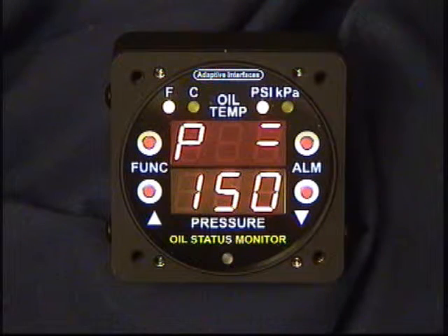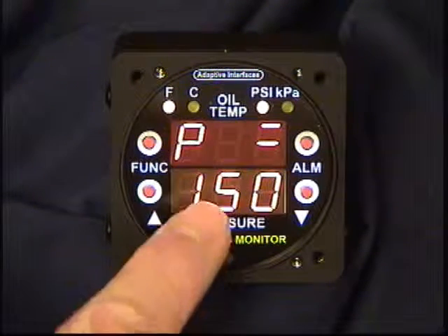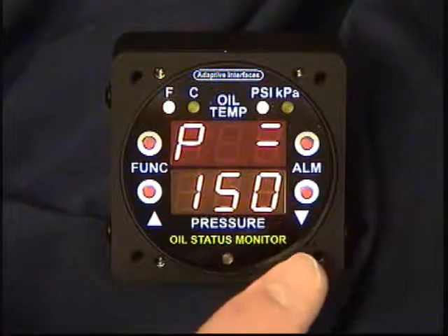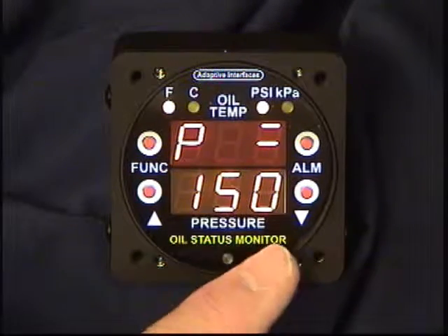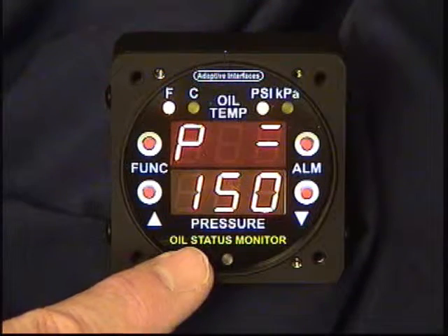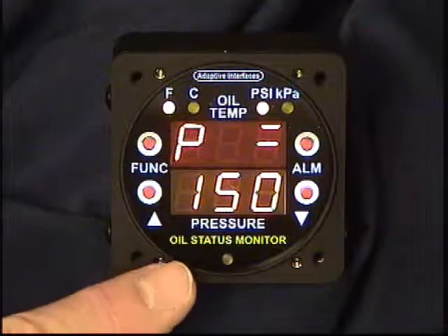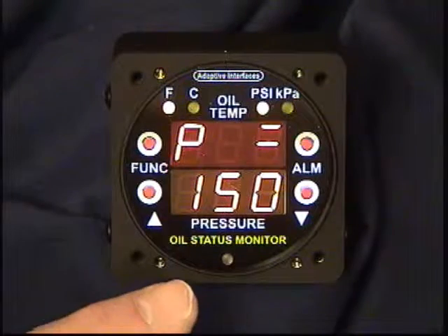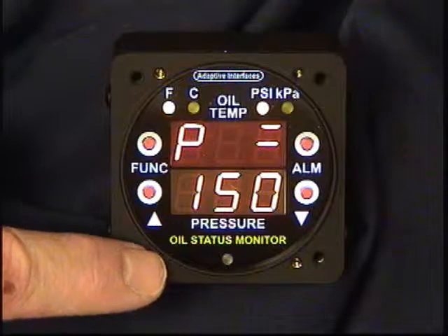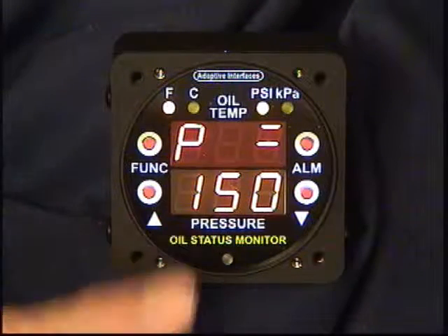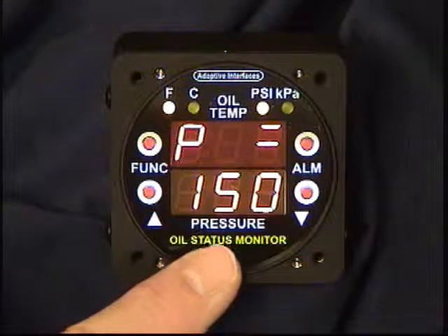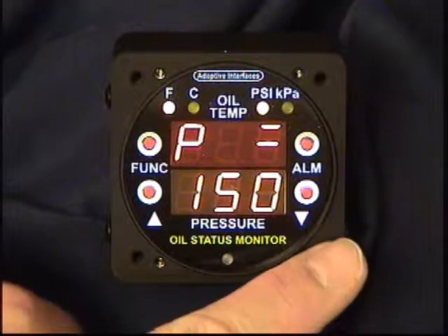In the case of an electronic sensor, this would be a value between 0 and 5 volts, and you'd be able to adjust it in 1/100th volt increments between 0 and 5 volts. If it was an LM335 sensor for temperature, it would always just read 335 because those are set values on that type of sensor. And if it was a current loop pressure sensor, you would be able to select a value between 4 and 20 milliamps.